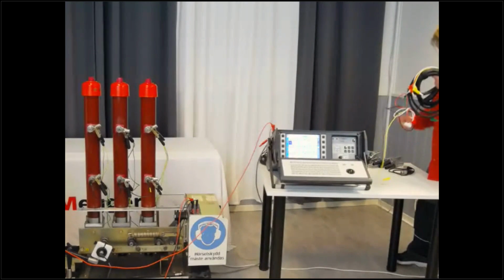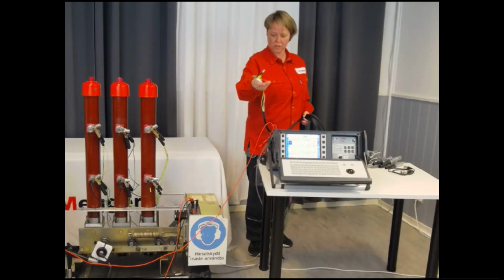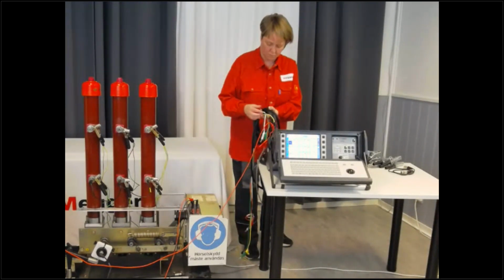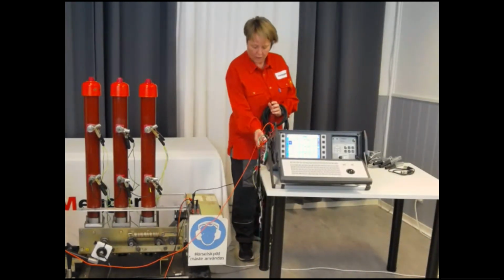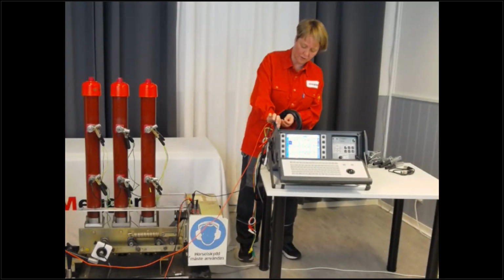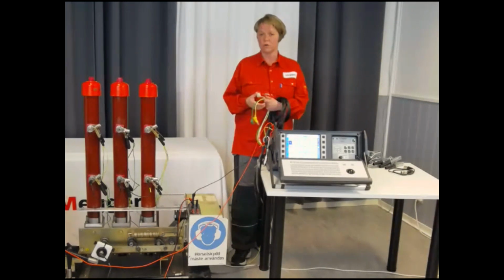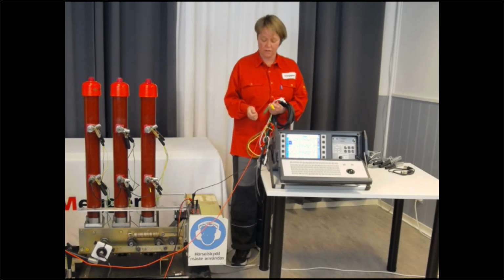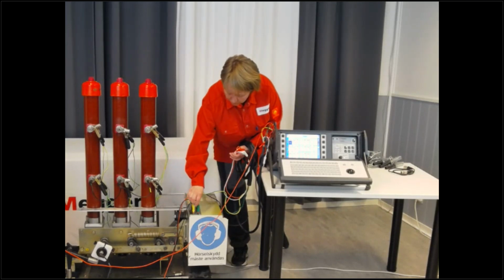But I'm going to use now the control cable set. One side, a shorter split. And I want to connect the minus I mentioned, to be able to measure the voltage. I want to connect also the close and the open command. You can't see what I'm doing here in detail. So if you want to see that, I recommend you go later to our videos on mega.com, where you can see the connection work in detail. It's much more complicated camera work than what can be done live. And close and trip to the object.